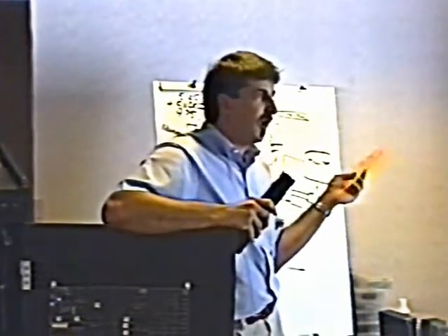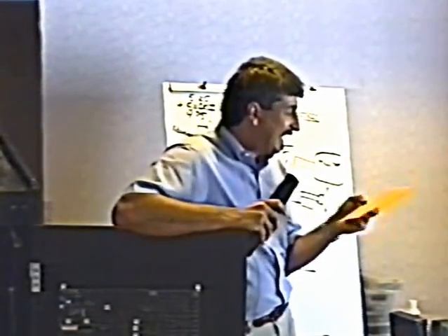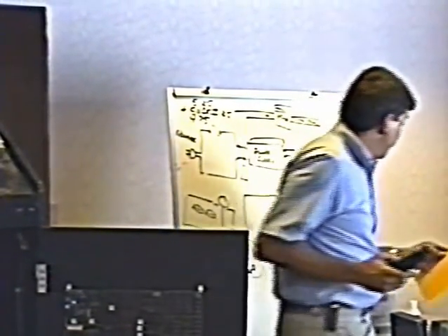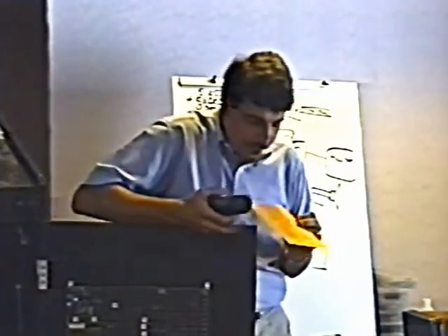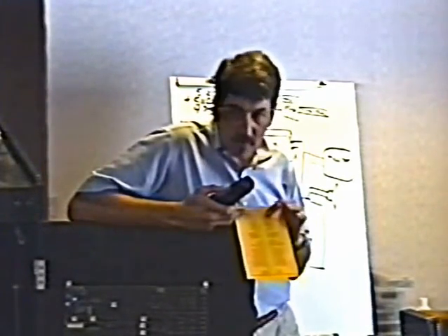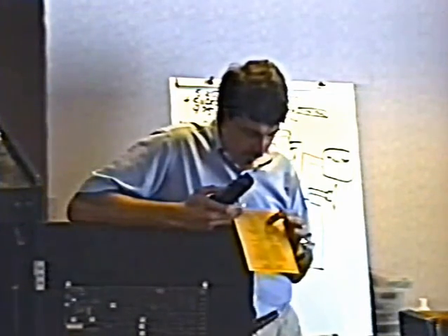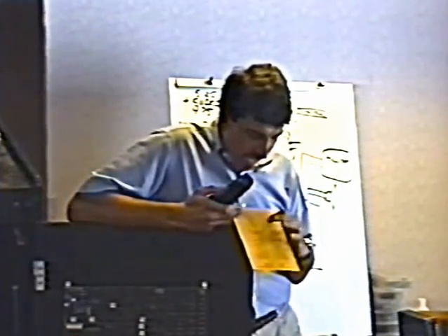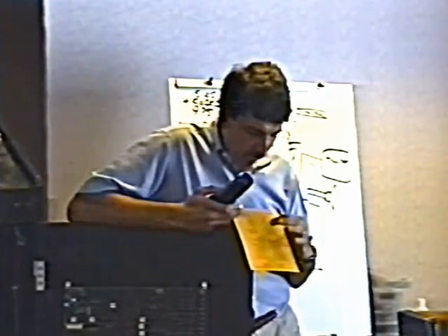The JAMA connector is a standard kind of harness that we use for really all video games these days. It's the same pinout for every game, meaning you can plug JAMA boards in from one game to another. You can see that the first two pins on each side are ground. The next two pins on each side are for the plus 5 volts. Pins 5 and E are for the minus 5. The next two are for the plus 12.